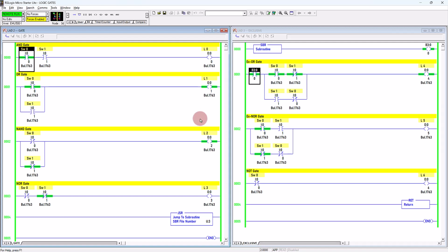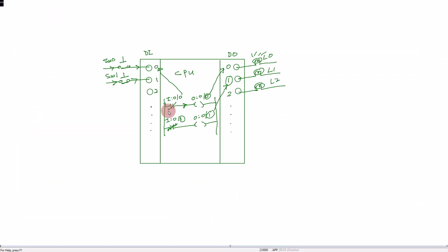Okay, so let's say the external switch, alright, this external switch 0 is open. Okay, then external switch 1 is pushed to close. So the actual current will flow through the digital input terminal point 1 to energize its internal LED 1. And this will cause all the relevant virtual switches to trigger, whether from originally normally closed to open or originally normally open to close.